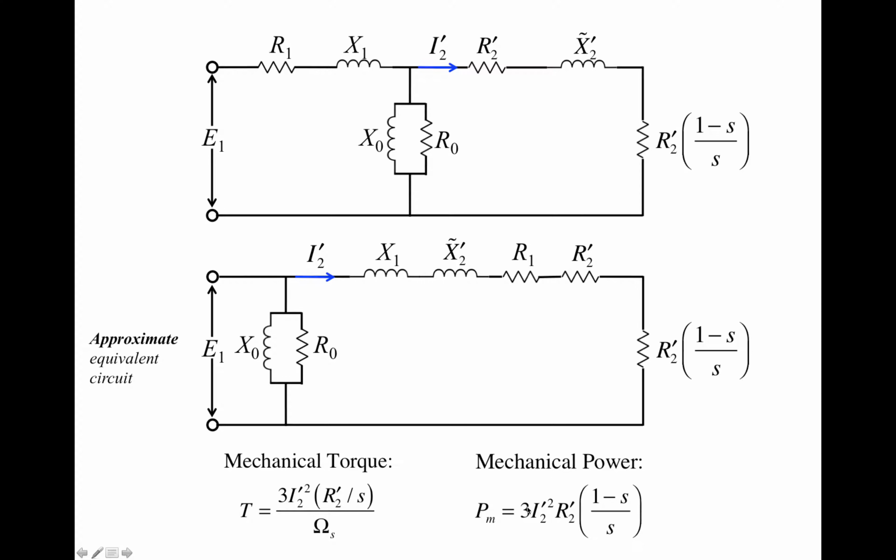The reason you have to multiply 3 is because you have 3 phases. This equivalent circuit is just for one phase, and for a 3-phase induction machine, you have 3 duplicates of the same circuit. You have 3 of these fictitious resistors, and on each of them you have a power like that. So you multiply 3 to obtain the total power of the 3-phase induction machine, right?